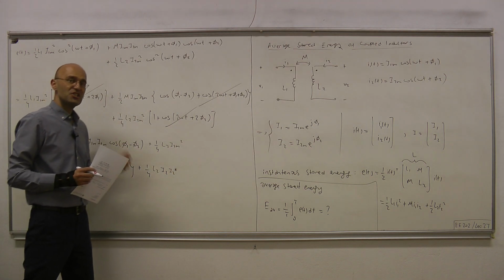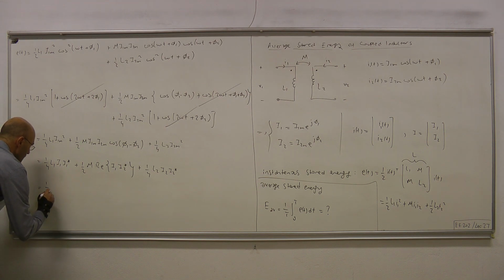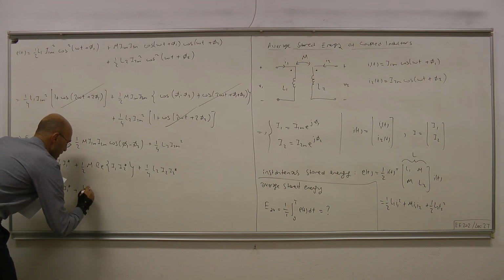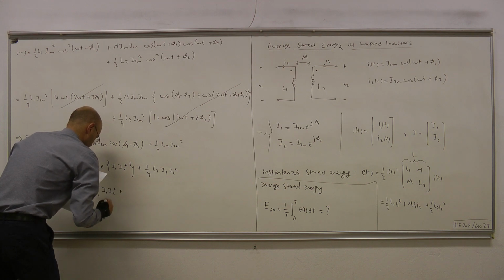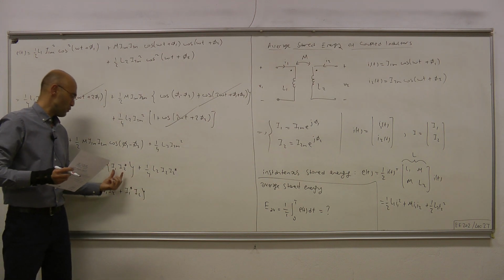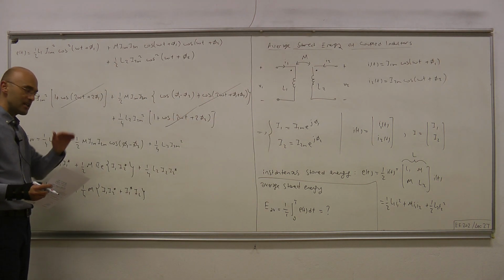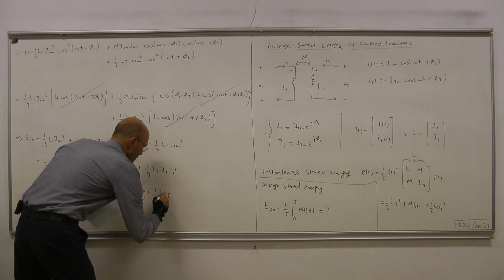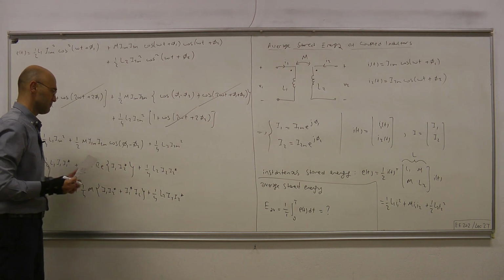Now there is one last step that remains, which is to get rid of this real operator, and that can be done by L1 I1 I1 conjugate plus, we make this 1/2, 1/4, and instead of this, we write I1 I2 conjugate plus I1 conjugate I2. Because the real part of a complex number is the complex number plus its conjugate divided by 2, and that dividing by 2 produces this 1/4 here. And finally, we have the last term.